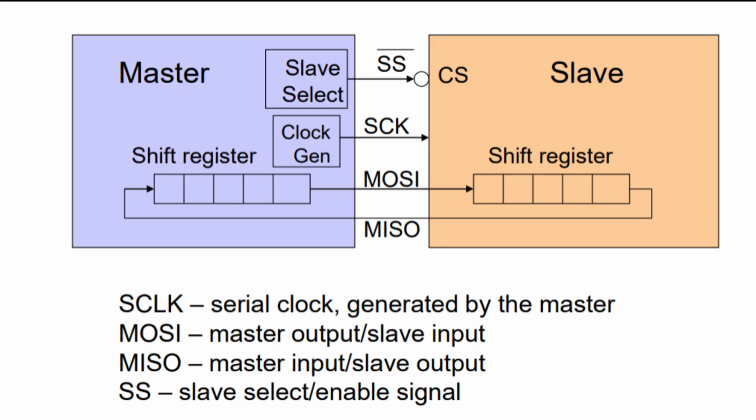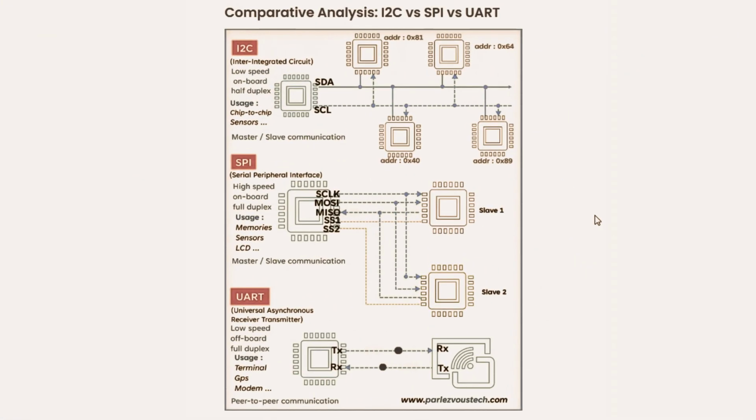And fourth, sometimes you might see a more complex handshake protocol defined for a specific device, perhaps where the slave responds with a specific acknowledgement byte over MISO when ready, after being polled by the master. Best practices. Use status register polling for simpler devices or things like flash memory busy checks. Definitely prefer using a DRDY or IRQ pin if the slave provides one, especially for real-time sensors where you want event-driven reads. Always check the slave's datasheet. It will specify the expected timing and how it signals readiness.